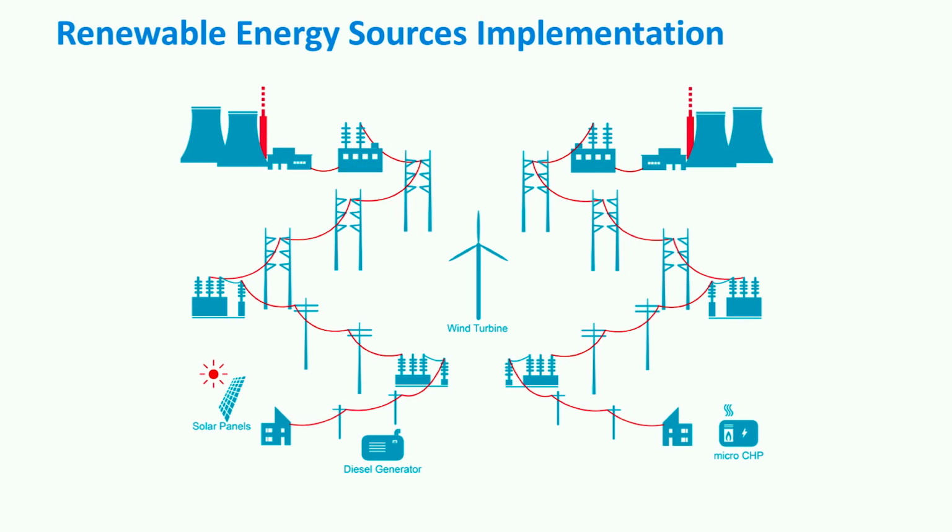For example, the introduction of distributed generation at the distribution side has the potential to raise a number of power quality problems, such as voltage variations and harmonic problems. The generation of active power at the downstream network has the potential to dramatically affect the flow of power in the upper network.